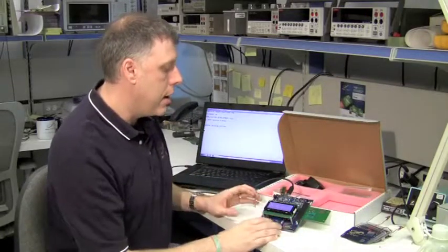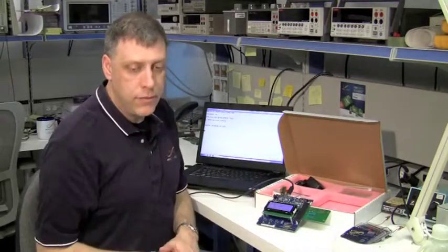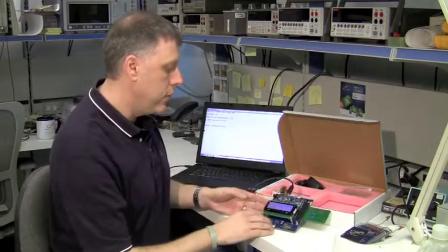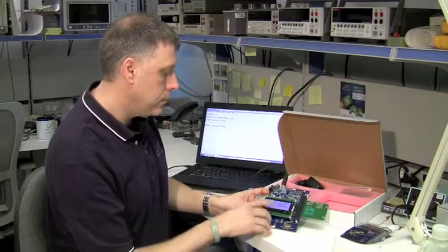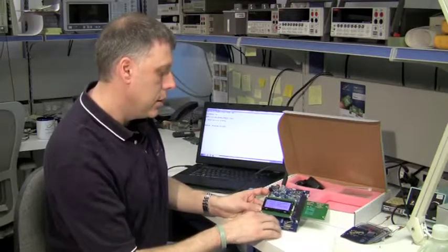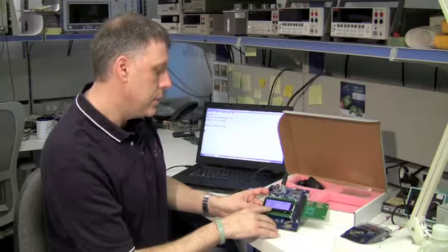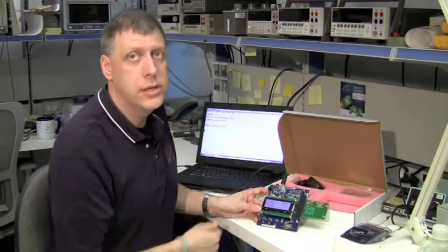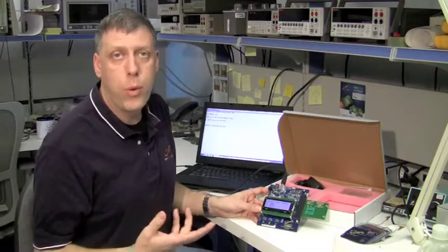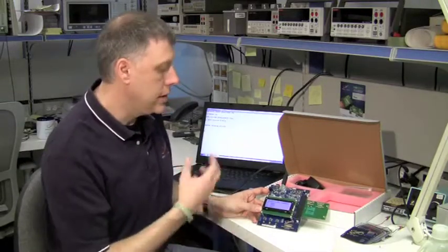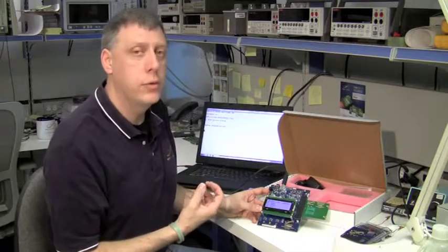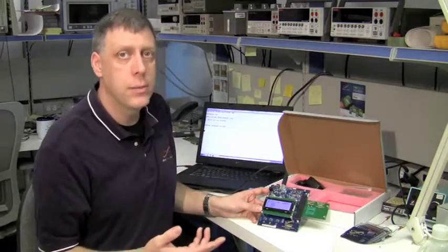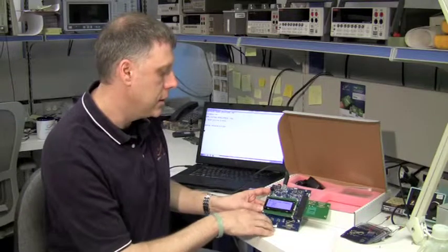So let's say I have an application that's going to require, for example, a 10 milliamp constant discharge. What I can do is go into demo mode, set the constant current, and then go through the options to the 10 milliamp. Now if you noticed, I can set an adjustable value too. So let's say that my current was 4.5 milliamps, for example. I can set a range from very low current, around 20 microamps, all the way up to the maximum current, which is 40 milliamps on the device.